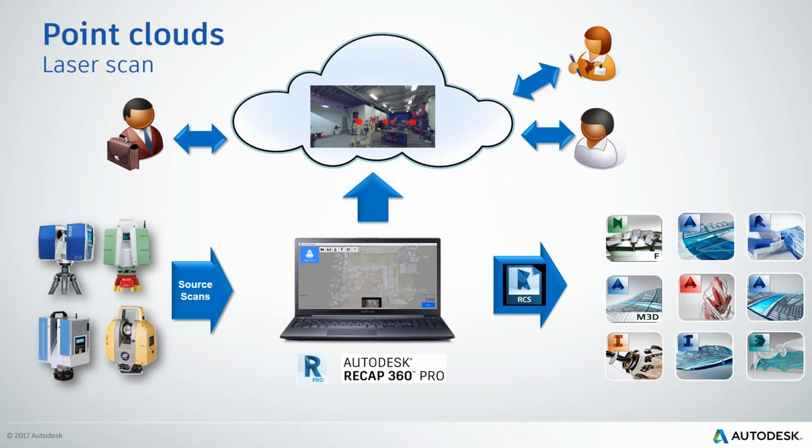Obviously, at the beginning, if you have source scans from Topcon, Leica, and other providers, they have different formats, so we have to process them through Recap Pro to have the possibility to use them.